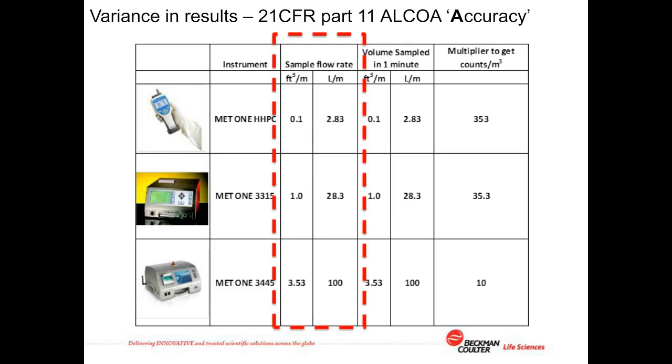And the reason it does flow at that speed is because when you are classifying or requalifying, you can sample an entire cubic meter, which is an EU GMP requirement for grade A zones, and you can do that in just 10 minutes.